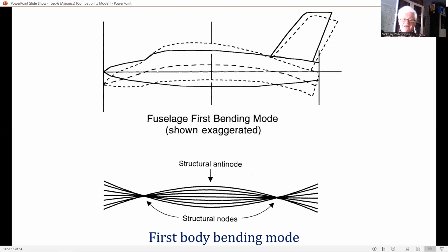There are also second and third harmonic modes at twice and 3 times the first body mode frequency, and possibly significant even higher modes. The tailplane, fin, and rudder have flexural and torsional vibration modes on their own, which couple with the aircraft structure.